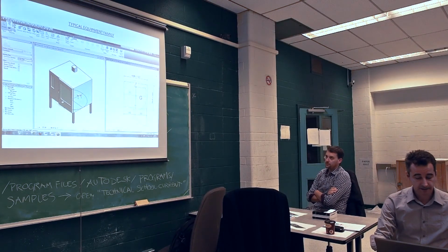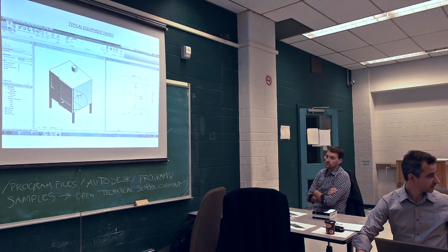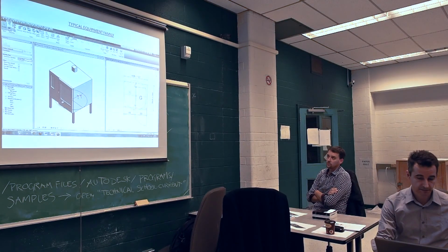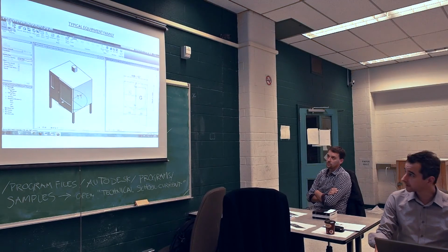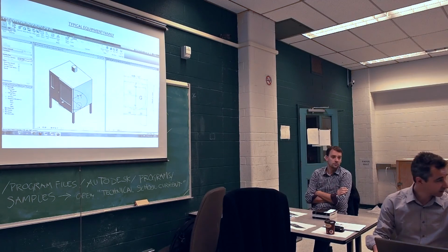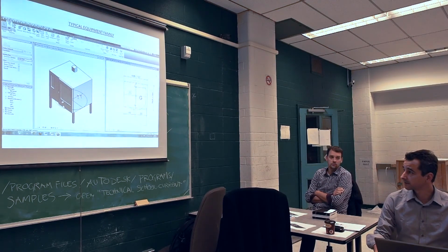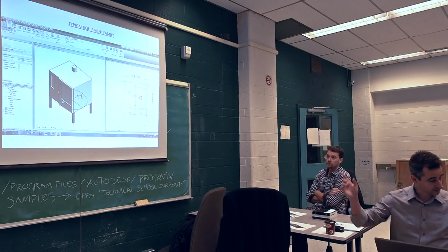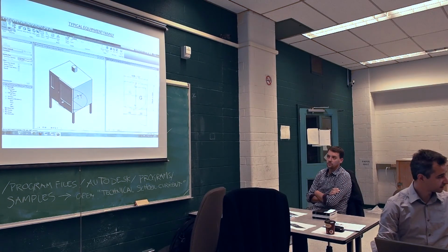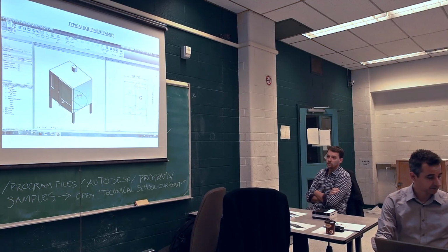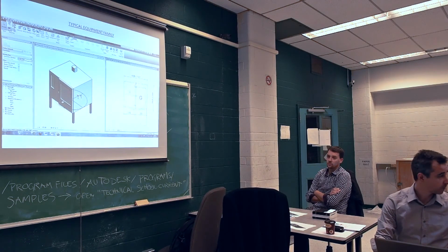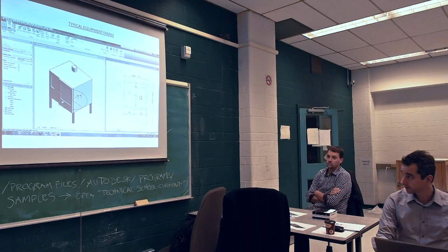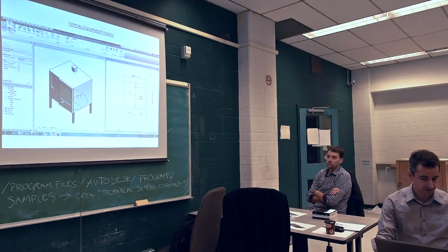And then, again, content families, we build thousands of these. Every single new piece of equipment is built in Revit, and all this green stuff that you see here, that's the power connection, that is the gas line, and this is drains. All that stuff is scheduled in something that we call points of connections, and they understand the power and engineering requirements for this equipment based on the location, based on count, based on many things.